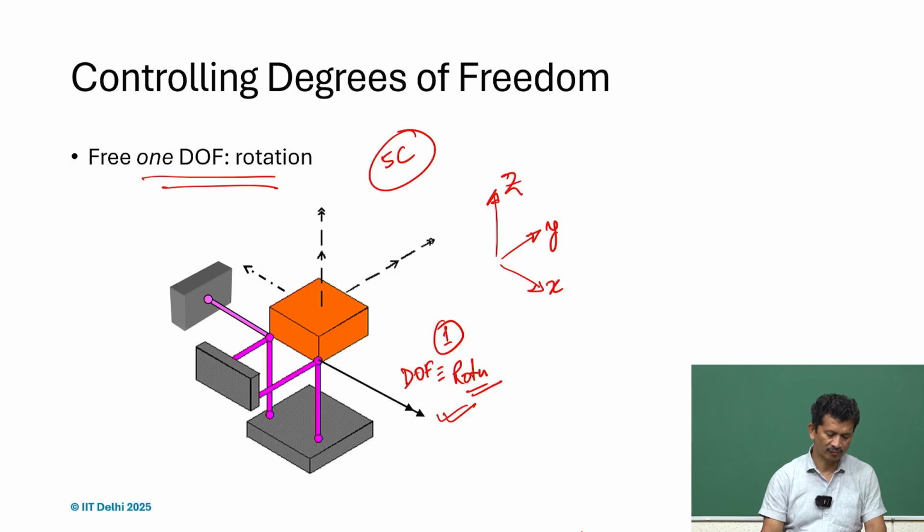So, yes, what we can say is what is desired is the rotation along x axis, and one way we can always show with the rotation, or we can use double arrows what we have here. So, 5 constraints, what are those? So, 3 translations we have to constrain and 2 rotation along y and z axis.